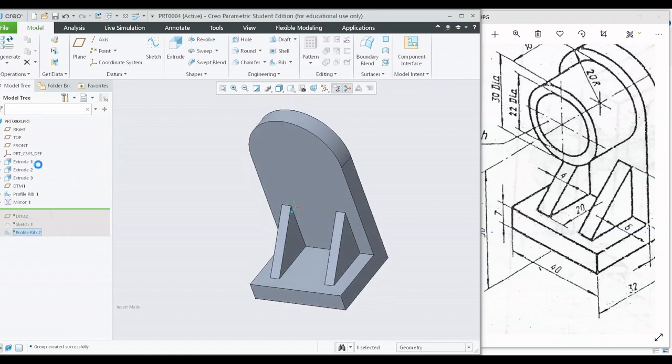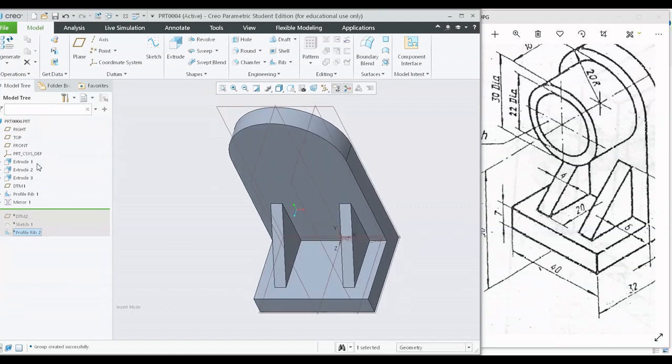So this is one of the most important features. For example, if you're creating a wing of the aircraft, if you're working on the right hand side wing, which is symmetric along the central axis, then you can generate the left side wing easily just by mirroring the right hand side feature on the left hand side of the central plane. That is called the mirror plane.